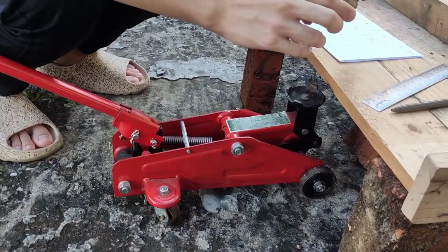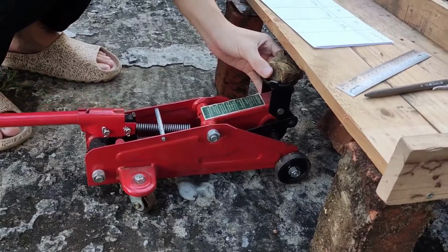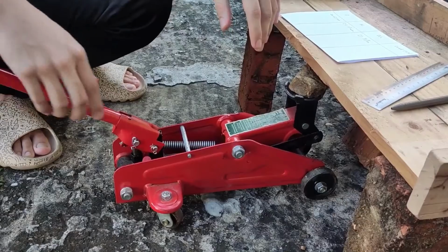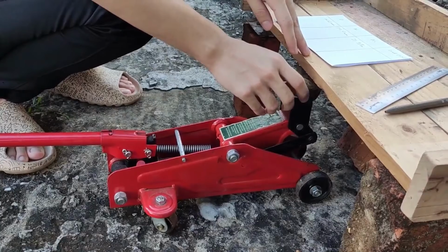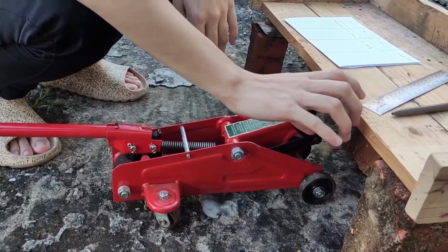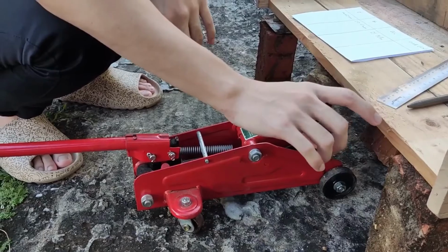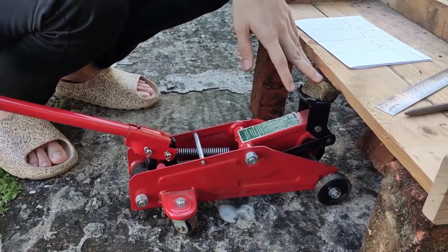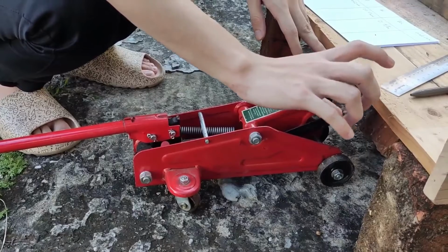We will have to put the rock sample in between the conical platen right until it touches the rock sample. As you can see, the hand pump is hanging. That is because if we continue to pump it, we will have started increasing the load and apply pressure on the rock sample. So right now, what we have to do is to erase the zero error. In the usual PLT apparatus, there is a load indicator. Here we should remove the zero error. Then we will slowly increase the pressure to the rock sample. As we slowly increase, the load indicator will also show an increase in value.